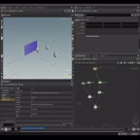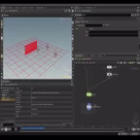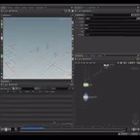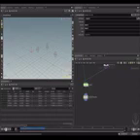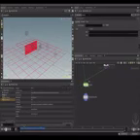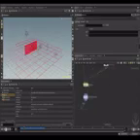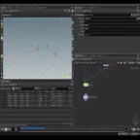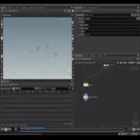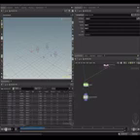That being said, let's jump back to SOPs. And let's see the impacts attribute we have here. For example, this one. If you remember, we only need impacts between 1 and 2, because those are the IDs assigned to the static object and the balls. So the object ID is the object ID of the spheres, and it's always 2.